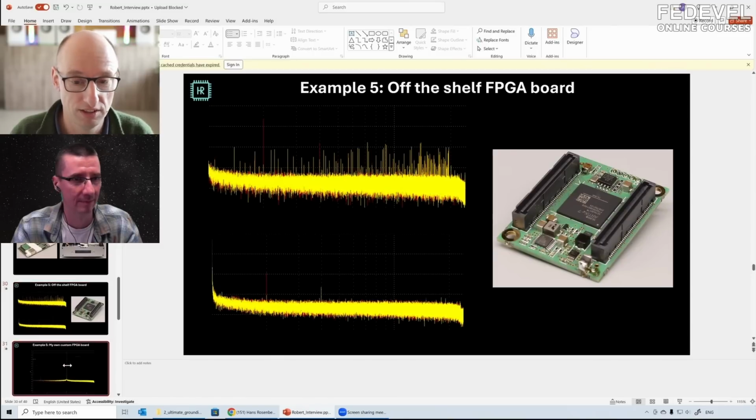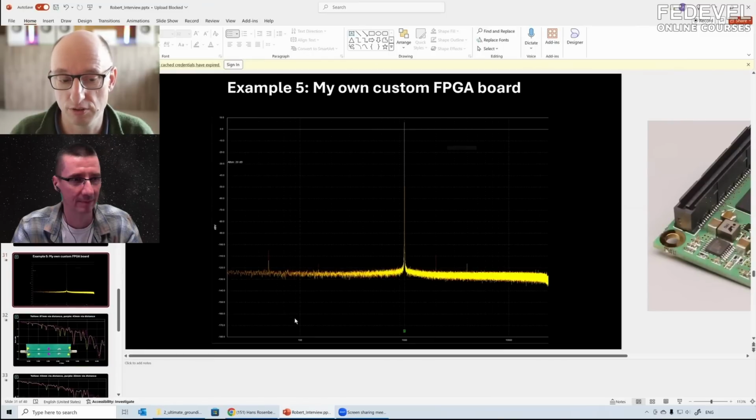I mean, this is another plot of the spectrum. Here you see a little bit of 50 and 150 hertz. That's the grid. That's 220 volts grid, so you'll always have that. It's very hard to keep that out. Here you see the 1 kilohertz. You see a little bit of distortion, but it's well within spec. Look, minus 110 decibels, and for the rest, it's completely clean. So that's a nice demonstration of